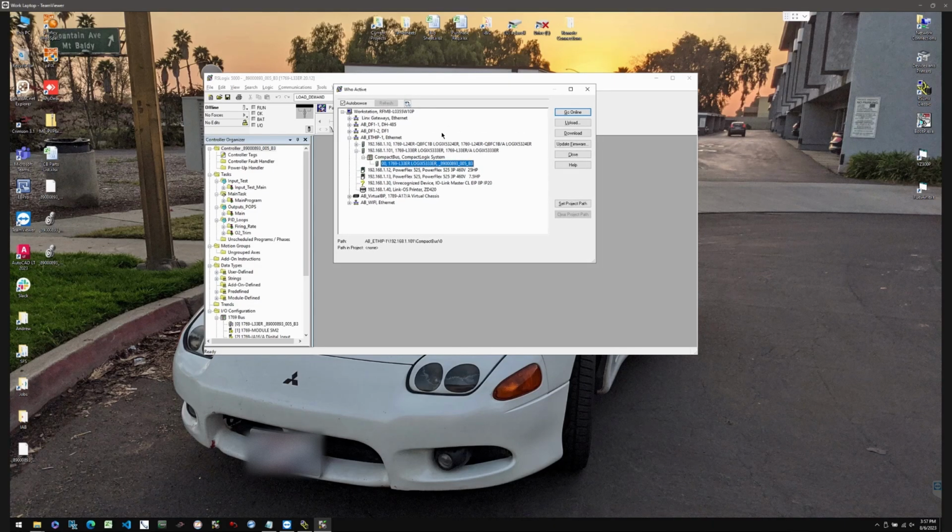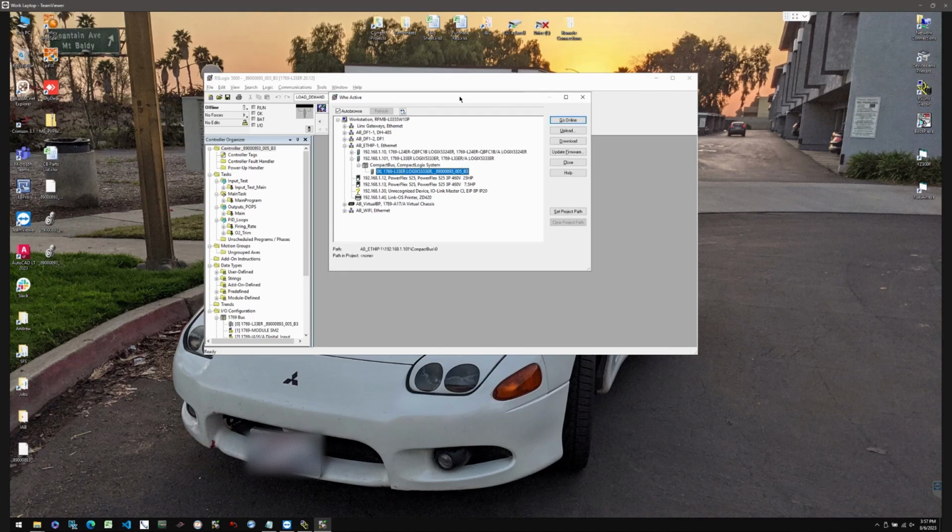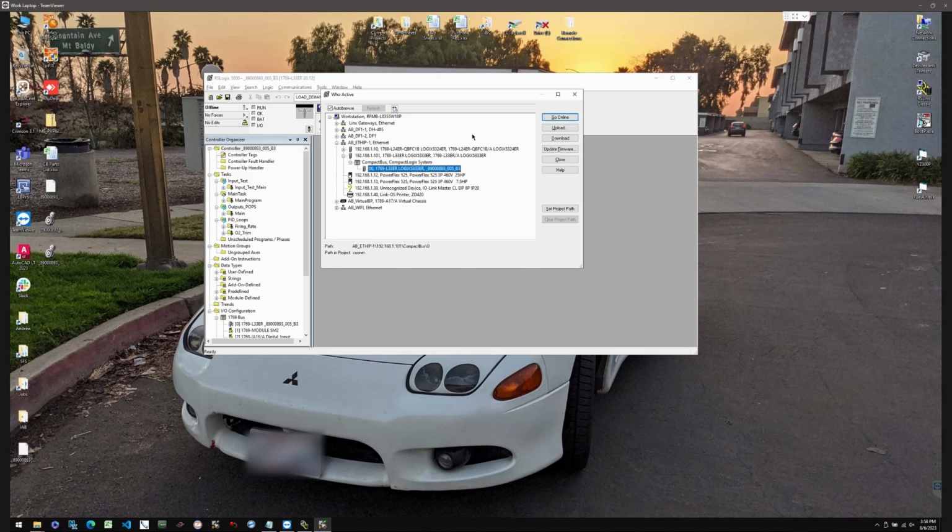Number one, it may be running right now. We don't want to affect anything while it's in operation. The number one important thing is if you ever need to download a program into the boiler or PLC program, we make sure that it's not running. We don't want to do that while it's running and cause any kind of issue. We shut that unit down, make sure it's isolated and there's nothing that's going to cause a problem, and then we will load it. Like I said, right now we're just taking a backup, so we definitely don't want to download anything. So that's why we always want to make sure that we don't have an open program while we're doing this.